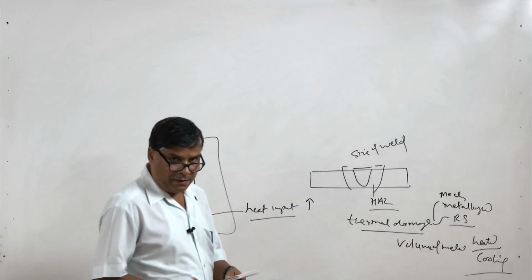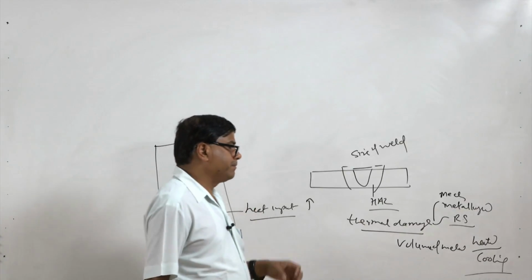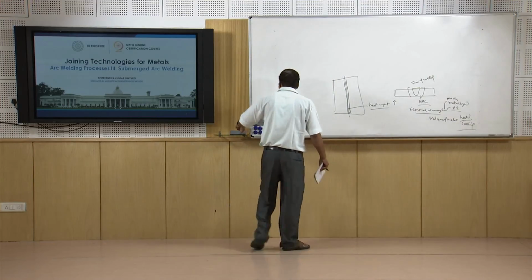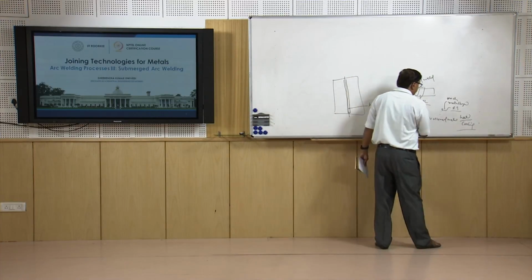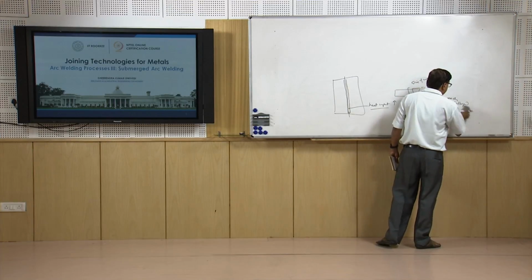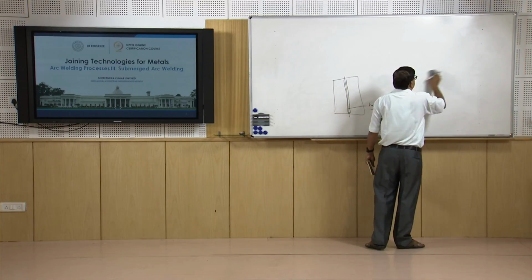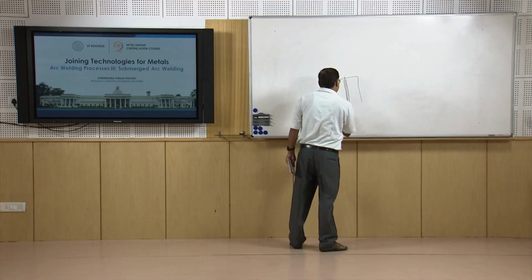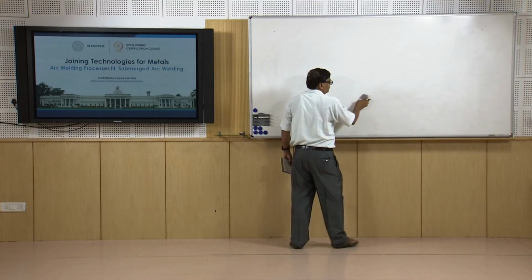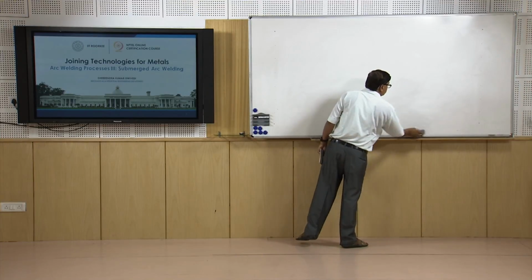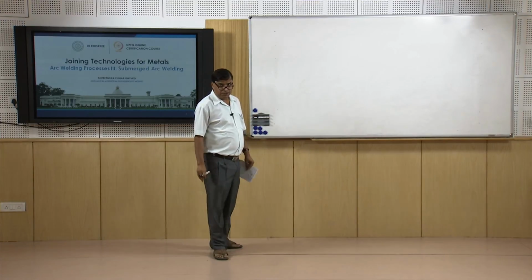Residual stresses are obviously tensile in nature in the weld joint, which in turn lowers the load carrying capacity of the weld, especially in terms of fatigue and tensile loads. So, it is not considered to be good. Further, the presence of residual stresses also promotes the distortion tendency, wherein the plates being welded using high heat input can go out of shape and out of the geometry which is not expected. So, that will require further post treatments to get things back in position.